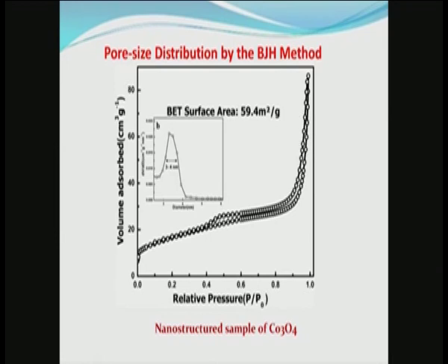So, what we have seen in this session is a description of the X-ray diffraction technique for measuring the crystallite size by measuring the broadening of the X-ray diffraction peaks and separating the broadening due to strain from the broadening due to crystallite size. One can determine the average crystallite size. One uses electron microscopy for detailed distribution of sizes.